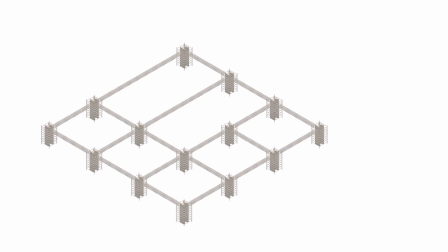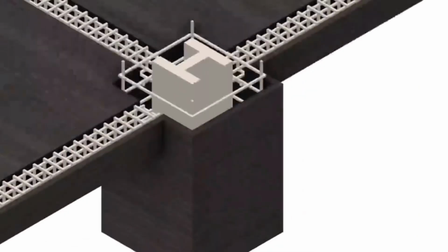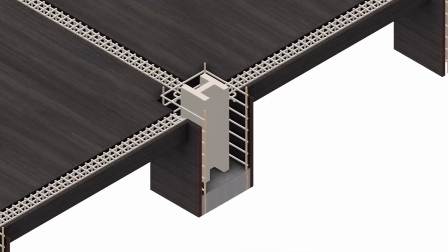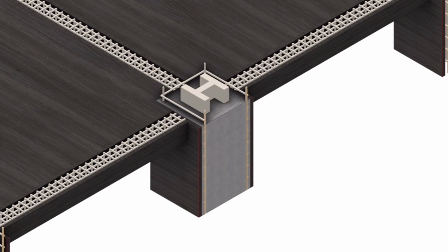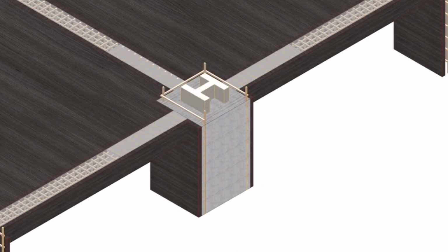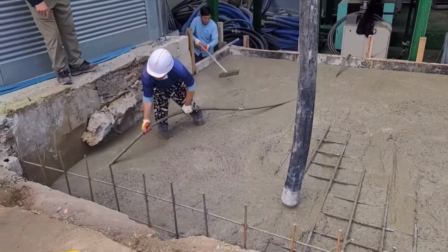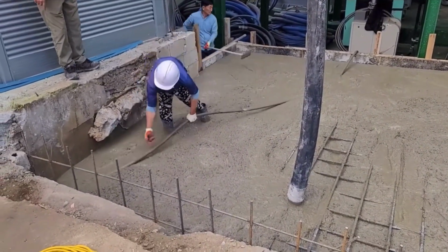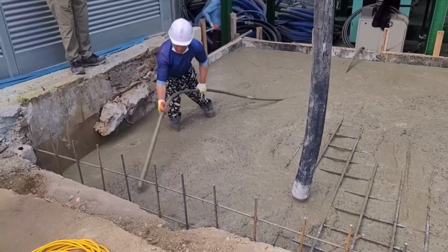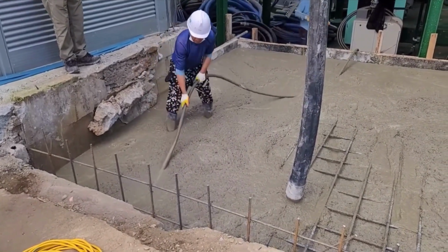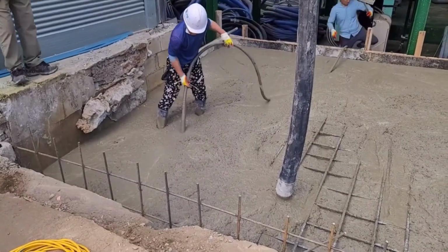As above, the columns and wall slabs are placed continuously after the reinforcement is deployed, and the air bubbles are removed through the vibrator to ensure that the concrete penetrates completely into the reinforcement.